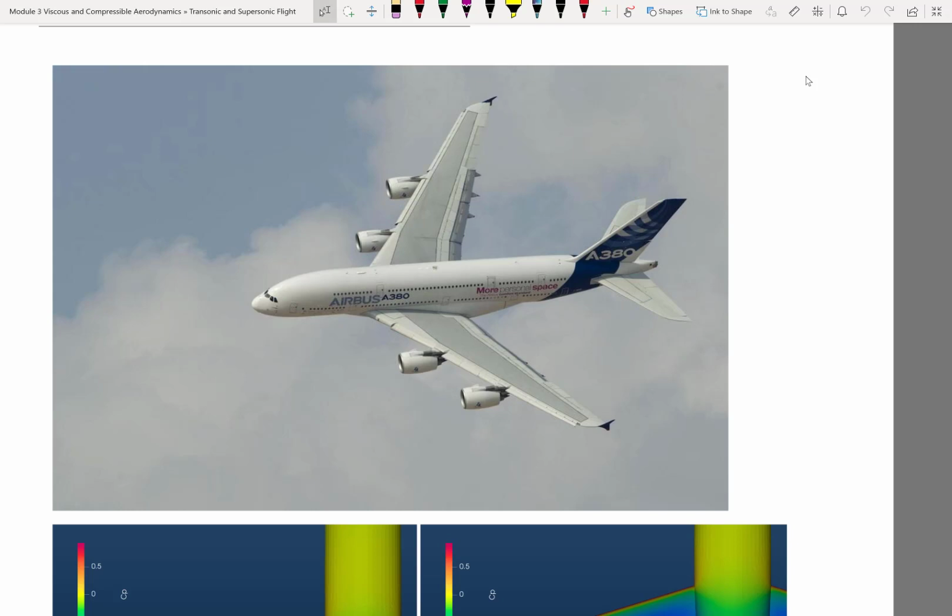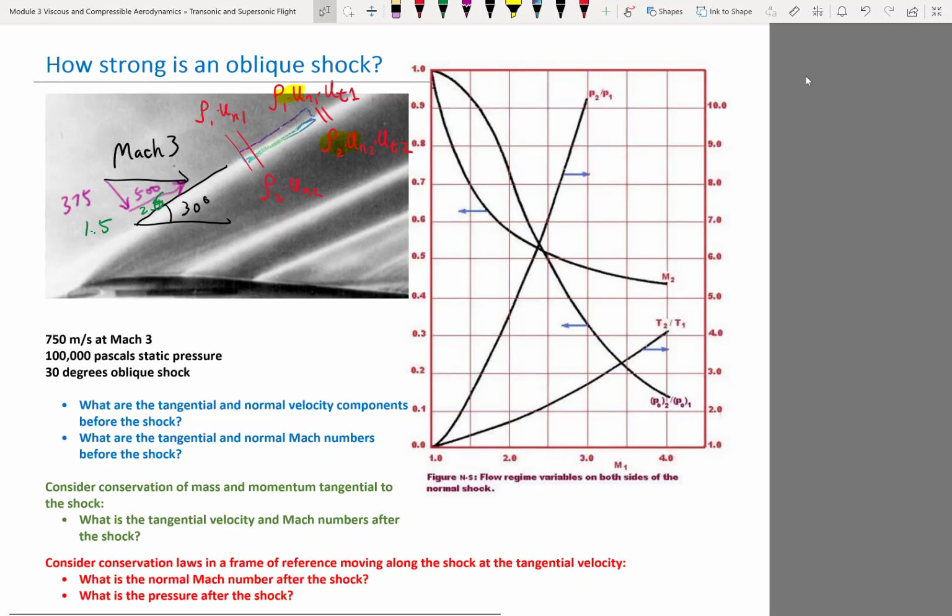By sweeping it back a little bit, you basically get a cosine of the sweep angle multiplier on the upstream Mach number. So if the highest speed is 1.2, this cosine angle is just enough to make the Mach number just slightly above 1, right? So you get essentially a very, very weak shock that basically has negligible pressure loss.